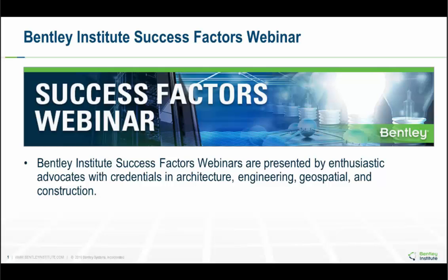In the direct analysis method, the residual stresses are accounted for by applying a stiffness reduction, tau sub b. Again, I go into more detail on that in the other webinar that I presented. In other codes and methodologies, those are accounted for by the K factors.